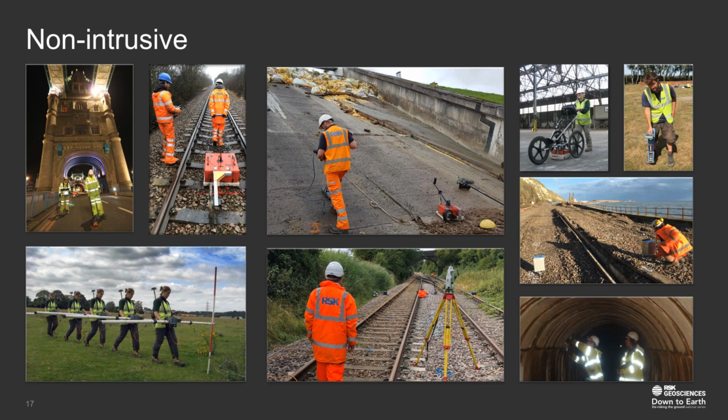Ground conditions, such as contaminated ground, landfilled areas, or even wet spots or wet beds, can also be identified with geophysical techniques, and it will produce a nice handy map that you can target your intrusive investigation with. Geological assessments can be done, so perhaps the variations in an embankment fill, the depth to bedrock, any faults or anything that might affect earthwork stability. Finally, you can also do structure investigation, so looking at floors and walls and soffits, but let's focus on the ground for now. It's always worth considering geophysics.